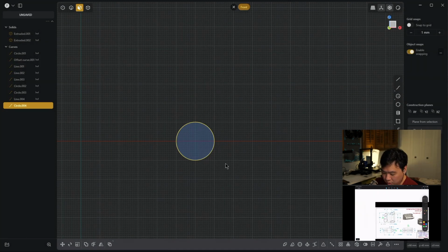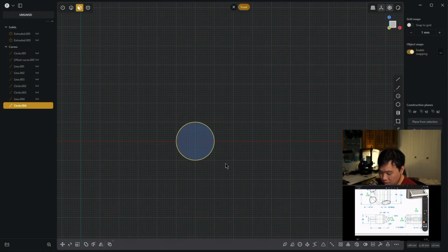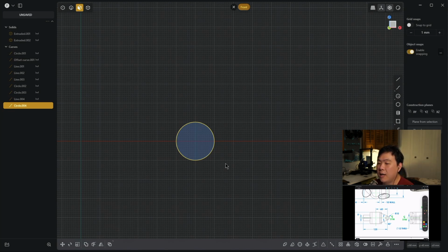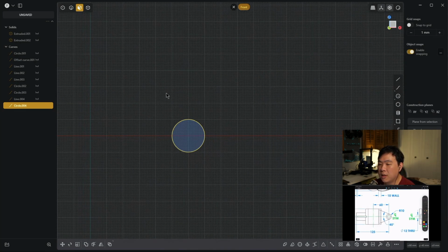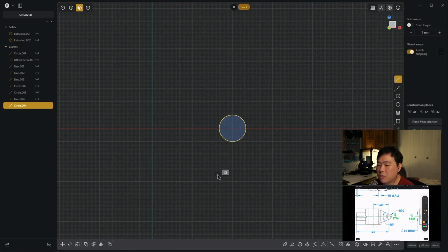And here we want to create that 45-degree angle tab. It's 45 degrees between the two edges along this x-axis. So really, we want the angle to be 45/2 in order for us to achieve that 45-degree angle. In order to do that, I'm just going to use the line tool, and I'm just going to draw anywhere first.